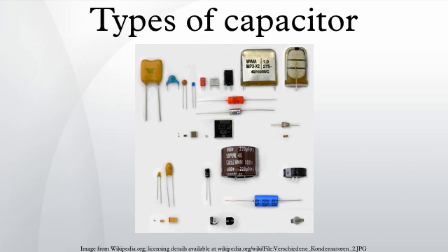The electrodes of film capacitors may be metallized aluminum or zinc, applied on one or both sides of the plastic film, resulting in metallized film capacitors, or a separate metallic foil overlying the film, called film foil capacitors. Metallized film capacitors offer self-healing properties. Dielectric breakdowns or shorts between the electrodes do not destroy the component.